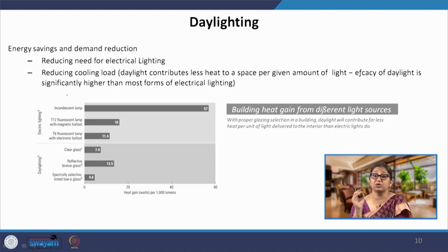There we can clearly know how much heat exchange is happening because of the glazing, and is it relevant enough, or how much of the wall should be provided as window for providing the daylighting. Are the savings equivalent to the extra energy that we require to remove or provide the heat? So, that is what we are supposed to see.